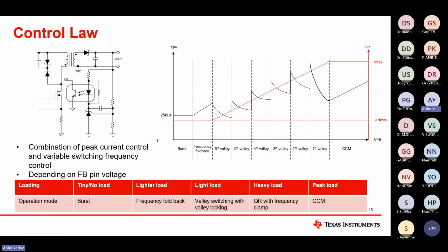So when our output voltage charges, it goes like this, and the overall average value remains constant. So what happens at a lighter load? We don't have any load to discharge this cap so much. So it skips the switchings, and switching will only appear when this Vout is discharged, to charge it again to maintain the required output voltage. So that is how the switching will only appear whenever the output cap goes low.